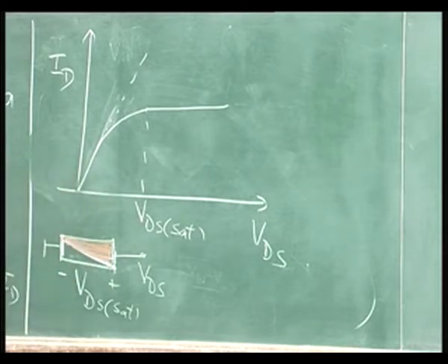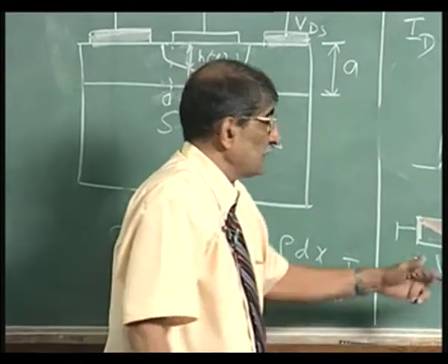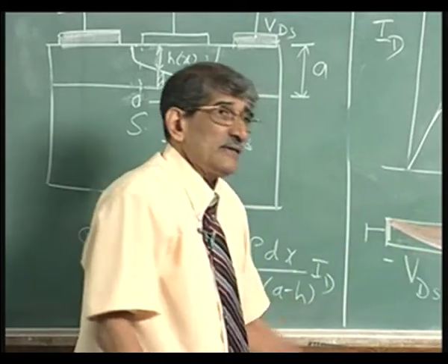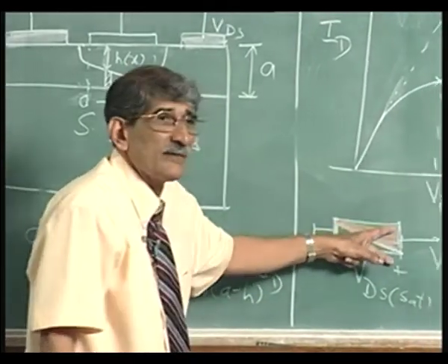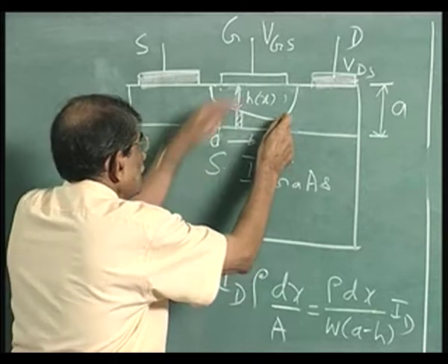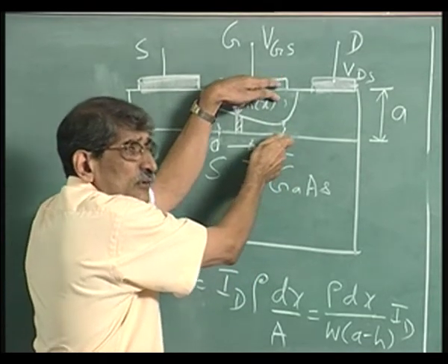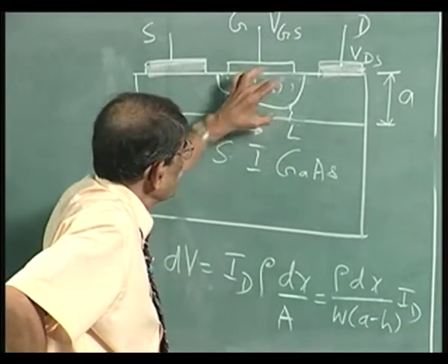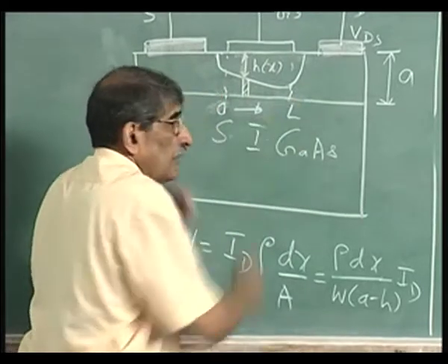So, now what we want to know is, what is this voltage, how much is the V d sat? We said that V d has saturated. Whether it is correct or not we have to examine later. It is quite correct for most of the devices; where it fails we will examine afterwards. V d sat is the voltage at which the channel has pinched off at the drain end. This has closed down this path. This has come all the way, it cannot close totally, but it is almost closing down. The opening is very small, finite. So, the V d sat, how do you find out?